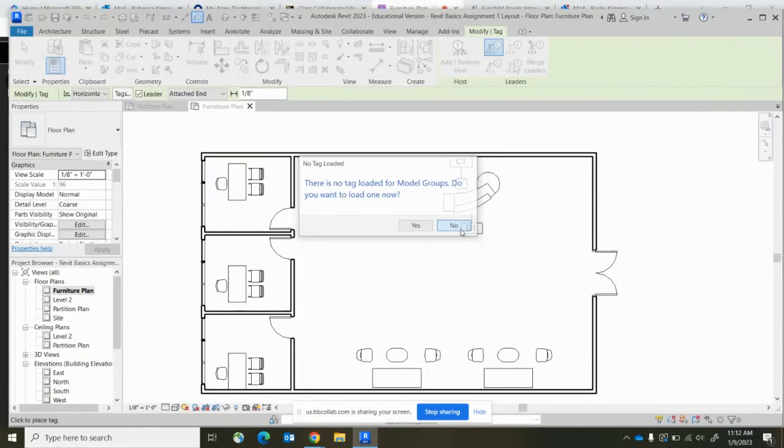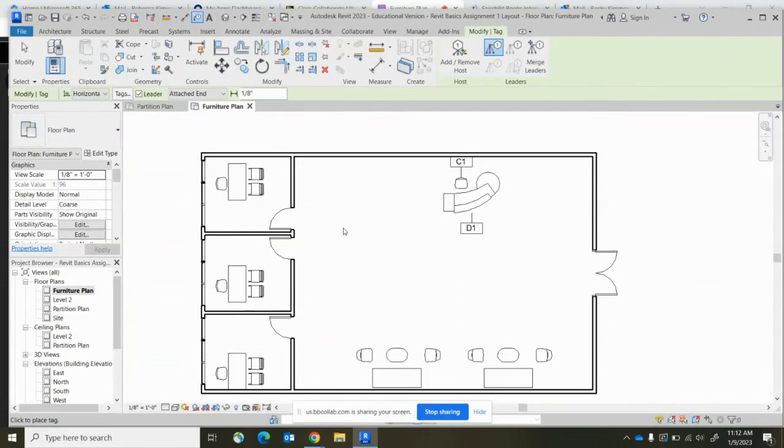So you can hit no, but you'll see, especially as we get into finished plans for Revit, there's a lot more, they will do groups of things. So like if this is a repeat of a desk two, another chair one, and then two chair twos, we'll say. Each of these is the same. So I can make this group, give it a tag, and then it will correlate back to a furniture schedule,